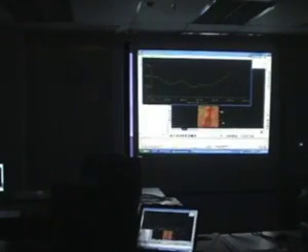And let's say I find, okay, I need to move this line. I'm just going to use a normal AutoCAD move on this line, move it to a new position. You can see how it updates automatically. So this saves you a lot of time in terms of creating a profile. Because a lot of people are still using a manual method, so you can imagine how long it takes. You just move the line a bit, you've got to do this all over again. It's not only about moving, even if you just readjust the position of the marker, it also updates.